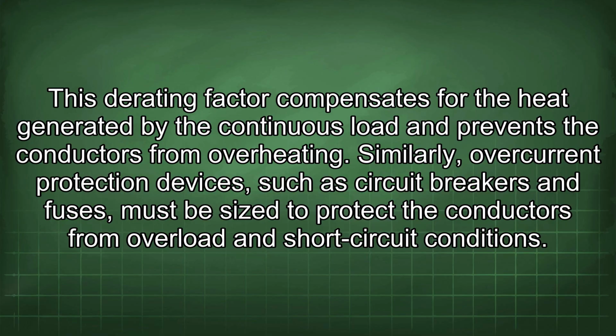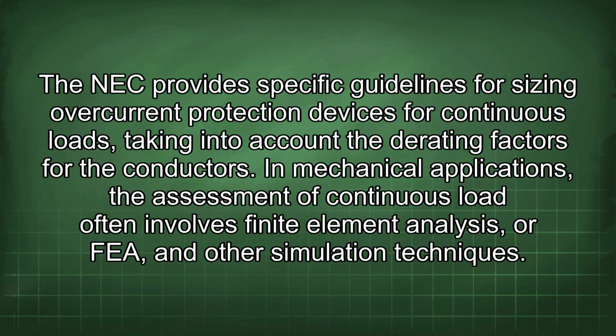Similarly, overcurrent protection devices, such as circuit breakers and fuses, must be sized to protect the conductors from overload and short-circuit conditions. The NEC provides specific guidelines for sizing overcurrent protection devices for continuous loads, taking into account the derating factors for the conductors. In mechanical applications, the assessment of continuous load often involves finite element analysis, or FEA, and other simulation techniques.